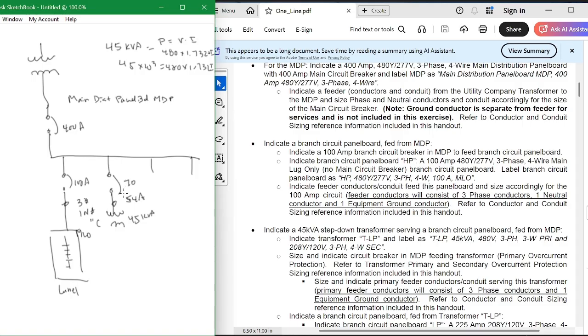Now, once you size that, this wire between here and here has to be sized for 70, because that's what this will let through. So you look at where's my break for what gauge wire. And typically you do not use odd gauge wire, you use only even gauge wires. When you get to larger sizes, you only use even gauge wires. Some people don't do that, but most electricians do not carry odd gauge wires. They carry even, so you have to go to the next even gauge wire size.